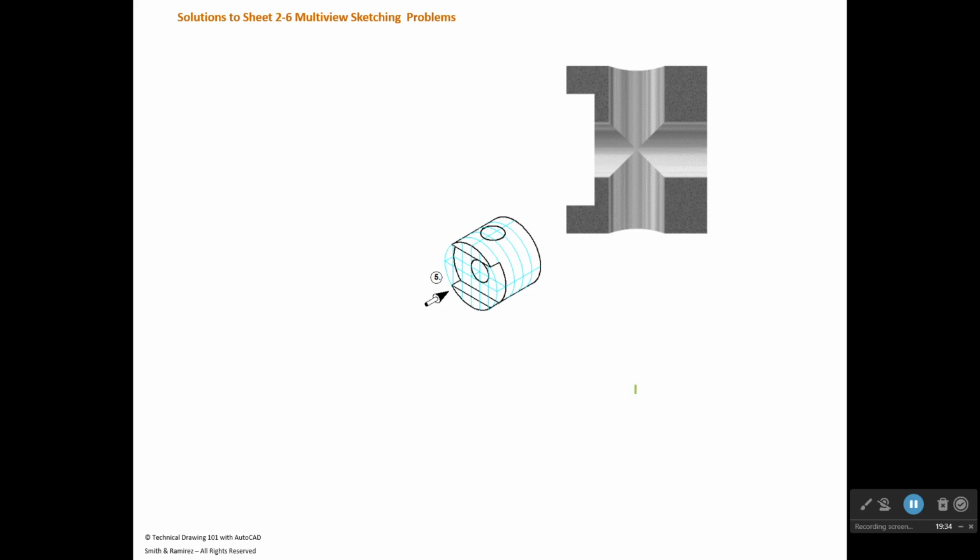Okay, so this is where we have two cylinders that are the same diameter coming together. So we have this cylinder here intersecting this cylinder here, right? And they are the same diameter, and so what we wind up with is right in here, we wind up with a V where those two come together. But actually it's up here, we have that small saddle where those two guys come together up there.